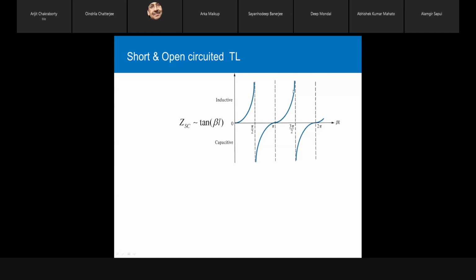Sir, by looking at the range of the angles, we can conclude whether it is inductive or capacitive. That means I can have one short-circuited line, and depending on its length, I can convert it to either capacitance or inductance, right? Yes, sir. That means at high frequency, and it is really true, for high frequency application, you cannot go to market and buy one inductance or capacitance. For high frequency business, the transmission line technique is the only technique to realize any reactance, inductance, or capacitance.